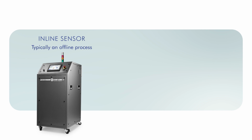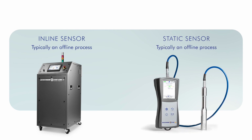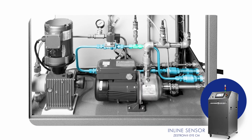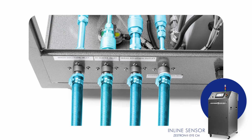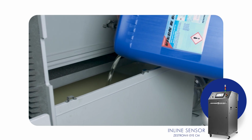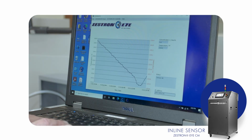There's basically two methods of sensors available in the industry. One would be what we would call an inline sensor. Another would be considered a static sensor. Basically, the inline sensor is installed in your cleaning system as the fluid comes through the wash pump and out through your nozzle system. It's moving through this inline sensor, and that sensor, in real time, is generating and calculating what the concentration of the cleaning agent is.